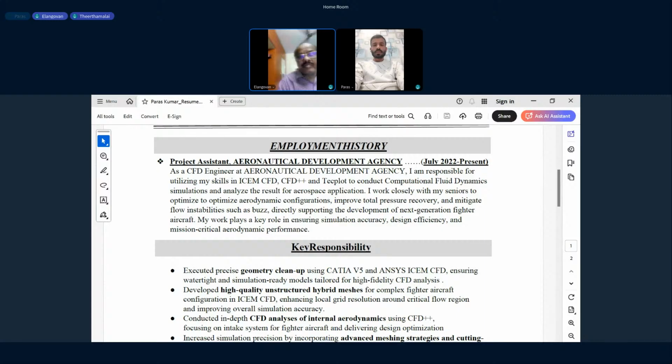Okay, they are all coming under secondary controls. What is the primary? Primary, sir, is, as an aircraft, it has how many degrees of freedom? Sir, the primary flight control is the rudder. The rudder is doing the yawing motion. Then elevators, which do the pitching motions. And sir, rolling moment by ailerons. Ailerons. Okay.